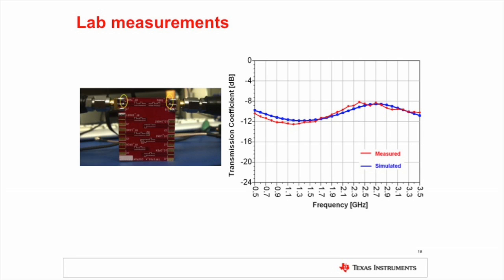Thus, care is taken while measuring devices at RF frequencies, and RF engineers make sure the measurement setup is properly calibrated and matched in order to avoid measurement errors due to ripples from the mismatch.